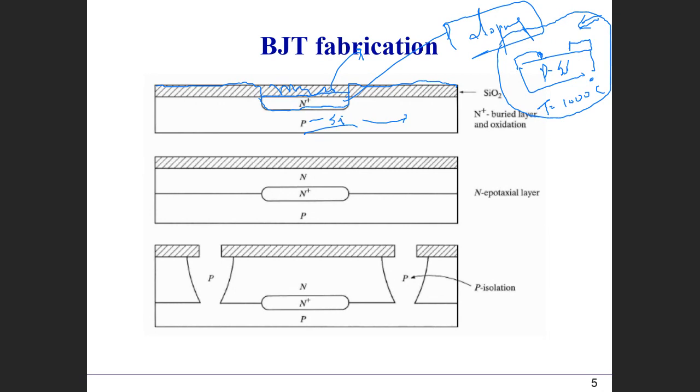So we put the N-type dopant into this furnace, and depending on the time, the open silicon region starts to have the N dopant diffuse inside the material. It depends on the time and the temperature, and other processing conditions. We can control this diffusion process precisely.